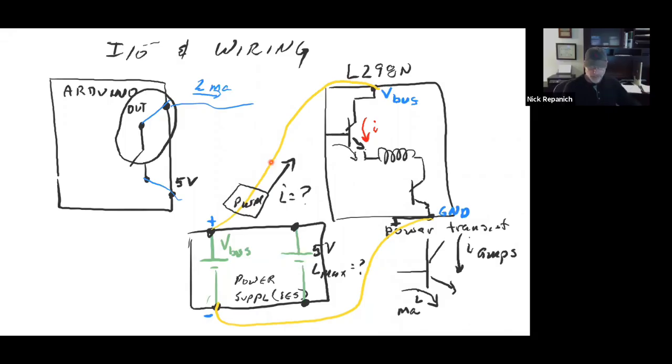So when I see circuits, this is what I'm going to want to see from you, is something like this that has the schematics that you're using, the schematical part that you're using of the individual components, some labeling. And to me, labeling means it needs to be labeled good enough that if you put this away and you get it out 6 months from now, can you wire it up according to this wiring diagram? Right? So label it and then show how to wire it.